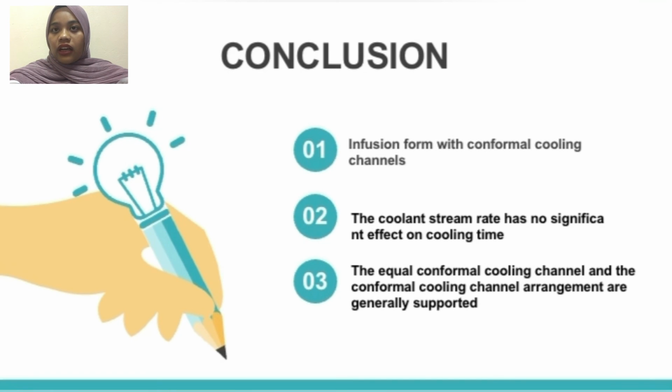The equal conformal cooling channel and conformal cooling channel arrangements are generally supported, although the conformal cooling channel arrangement is strongly suggested as an answer for improving the efficiency of the new product in the technique of injection molding.